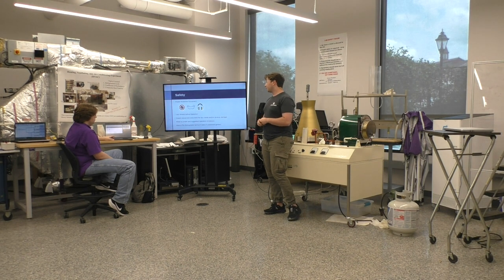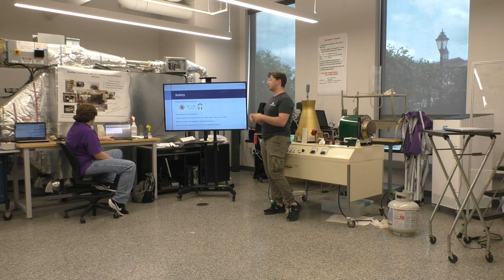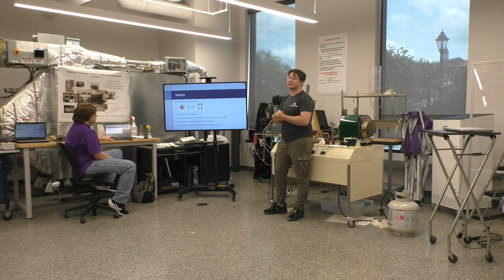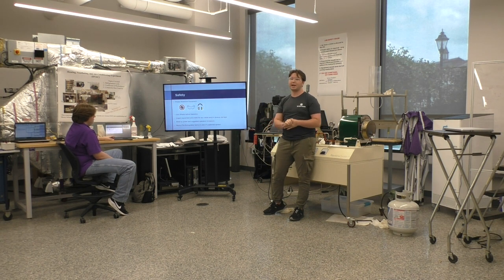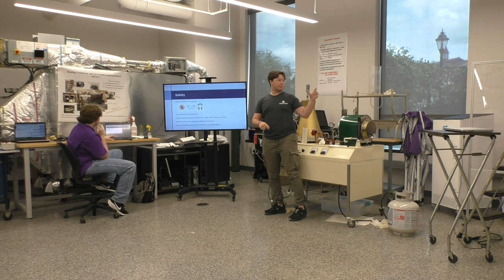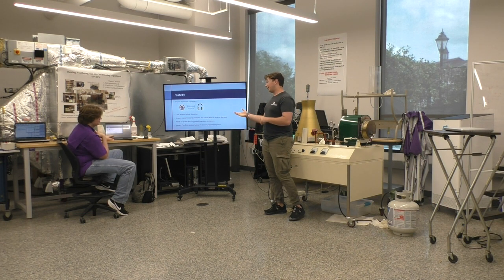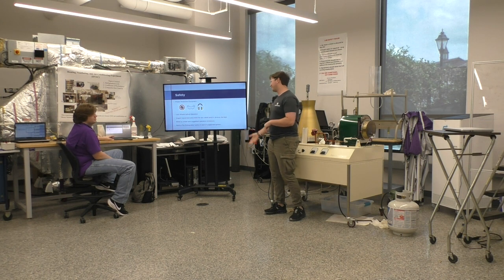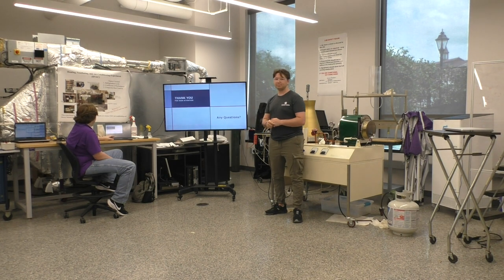And lastly, for safety, we have to wear proper PPE, so that includes shoes, safety goggles, and then for this one specifically, hearing protection, because it does get loud. We want to make sure we lock the wheels before operation, because it is mobile. It gets really loud, so ideally you would bring it outside. When I inspect the equipment, make sure there are no cracks or oil spraying out. It does happen, and have a fire extinguisher handy in case the spraying oil catches on fire, but that's it.